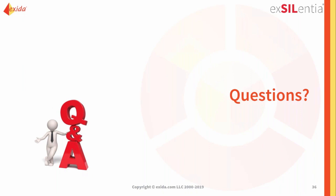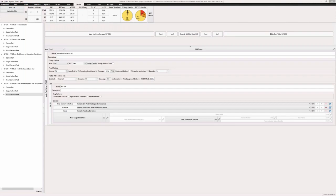It all depends. If we go back to the software here and we go to this most extensive test, let's go to a 1 year test interval for now. Obviously we're not meeting the SIL 2 requirement that I put in here. So in this case, with the equipment that I've selected, keeping in mind this is generic equipment, and our generic equipment is intended to cover around 90% of what is available in the market.